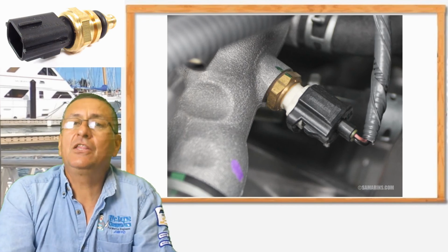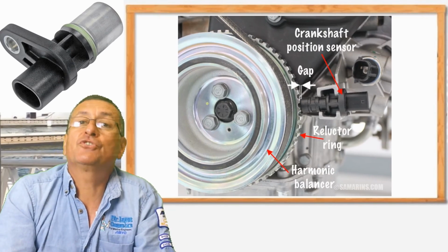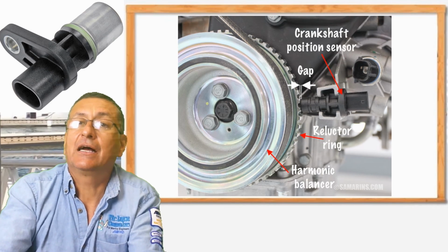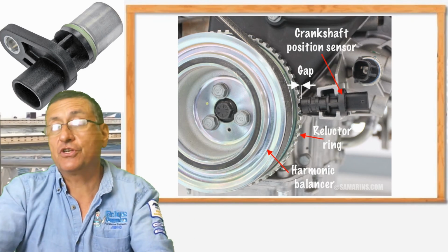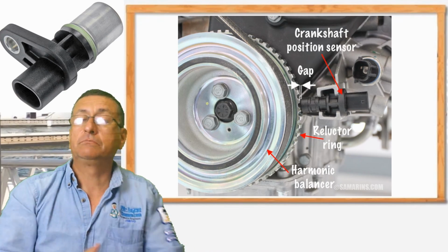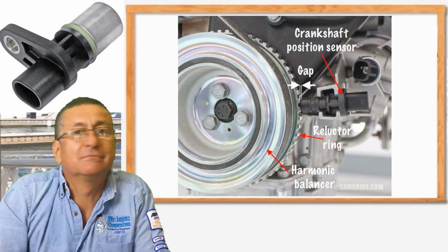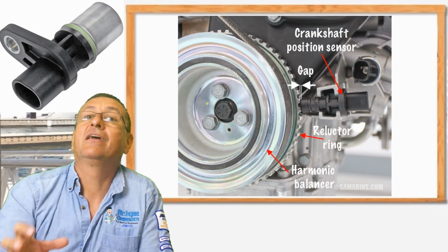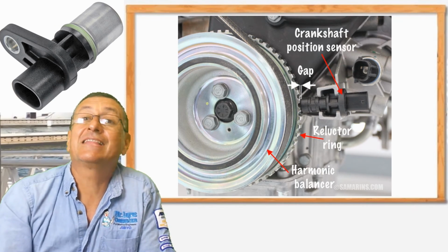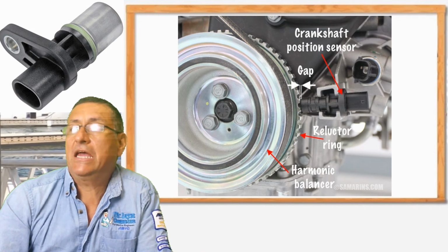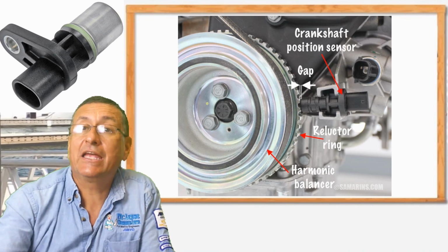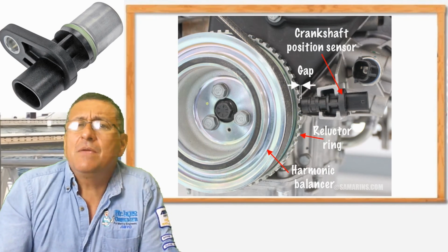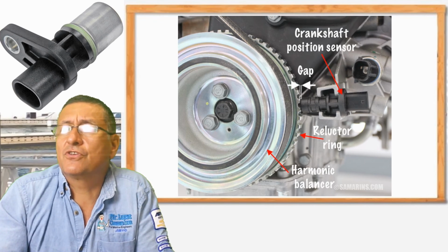We can play a little with the crank position sensor. For example, we can disconnect the crank position sensor and now try to start. The engine doesn't start because we don't have the signal reading the timing. After that, connect again and start the engine, and the engine starts immediately. This is a simple way to identify if the crank position sensor is working.